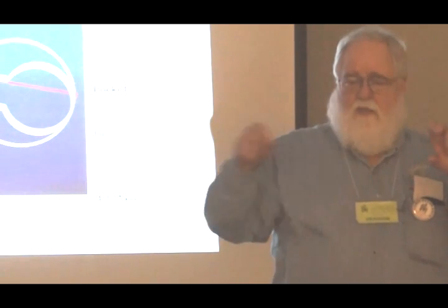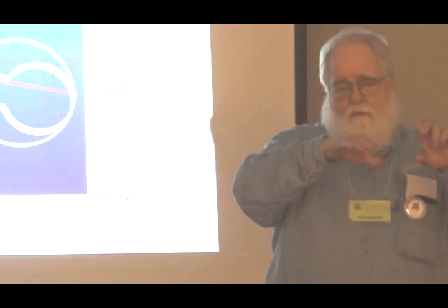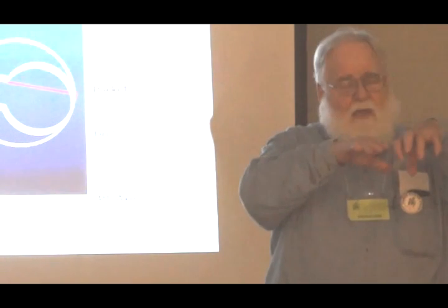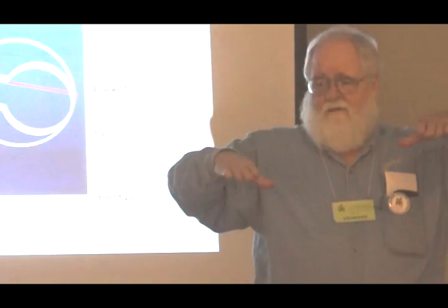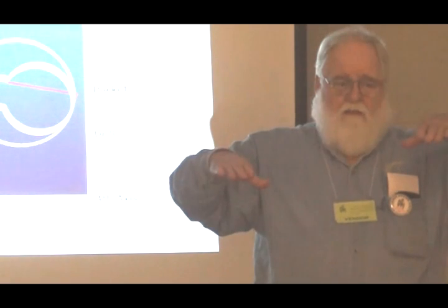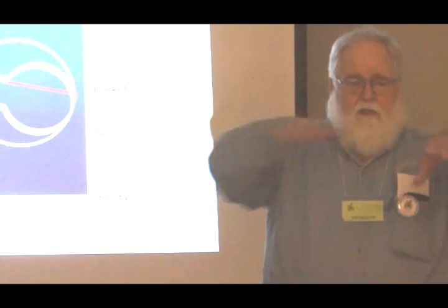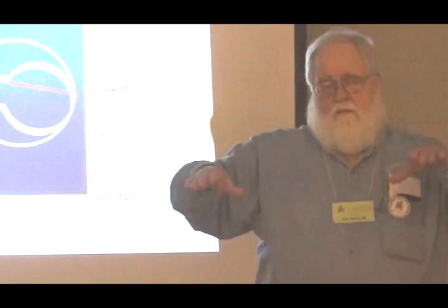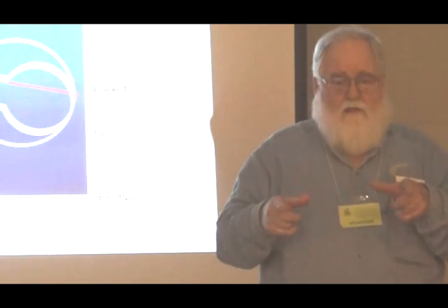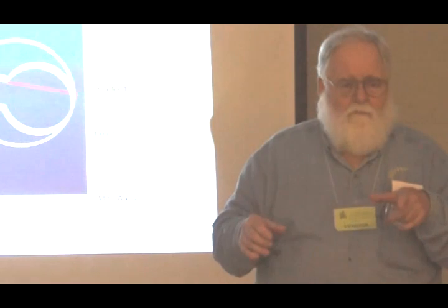Then I made a rectangular pocket that took out everything except the top cylinder, everything over to the end, by the depth being the distance in height of those two rectangles. Okay? So I did a rectangular operation to get down to the first level, and a second rectangle to get between the towers. I took all that out with a separate rectangle.